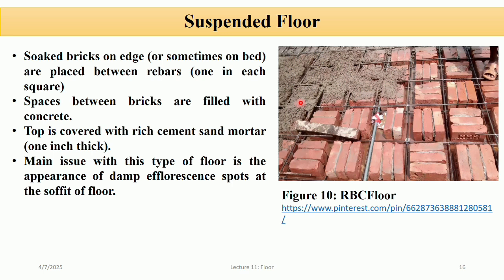After pouring the concrete, we have to provide the top cover with a rich cement sand mortar. The main issue with this type of floor is the appearance of damp efflorescent spots on the surface of the floor. This method provides moderate strength and is best suited for residential buildings where the load is not very high. It is a practical solution in areas where cost saving and material efficiency are important.